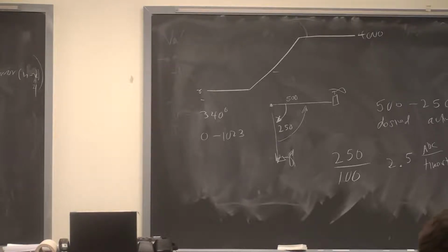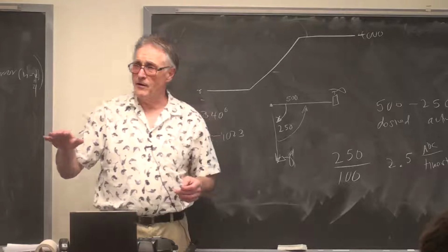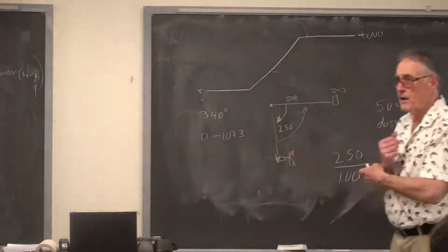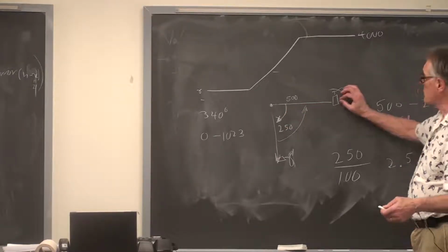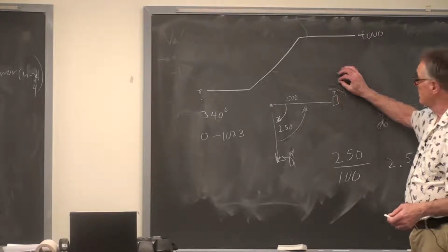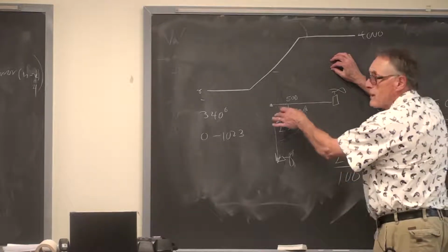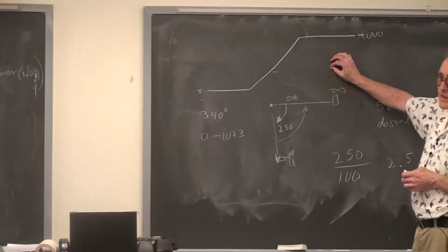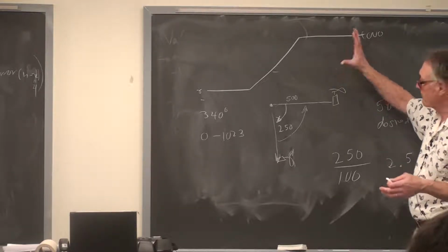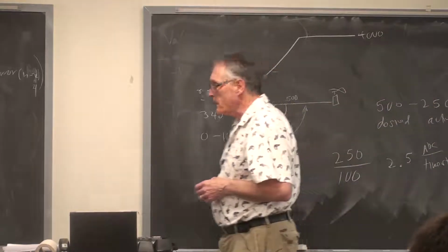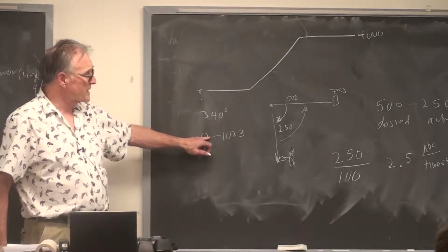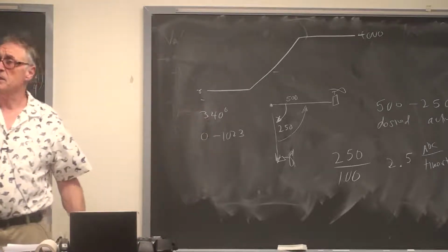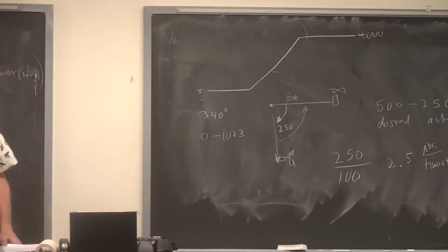Well, you could easily have this hooked to an oscilloscope from day one. Hold this horizontal, measure the voltage. Put it at 30 degrees using the protractor that is in the lab. Measure the voltage or measure the resistance. Or you could calculate it based on the fractional rotation. If this thing goes through full scale in 340 degrees, you can calculate what 30 degrees is going to be in terms of ADC units, and that's good enough.